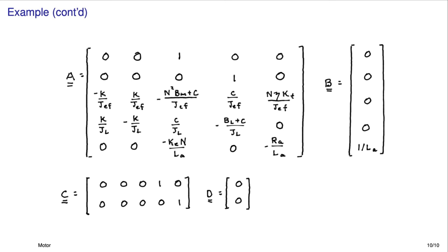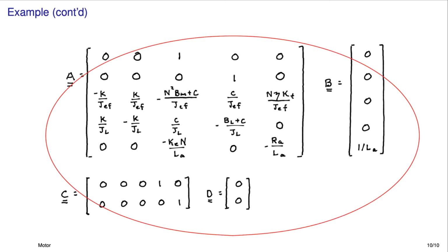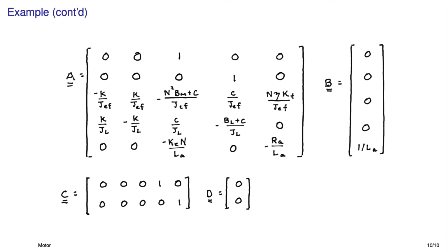So there we go. Now what we'll do is go into MATLAB Simulink, and I'm using 2020A here, and in particular I'm going to take this state space system and throw it into a state space block. That's pretty easy to do, but then also model the system using some of the Simscape blocks, and that will give us two versions of the same model, one formed with state space and the other formed using the components from Simscape. And if we're lucky, the response of those two models will be identical.